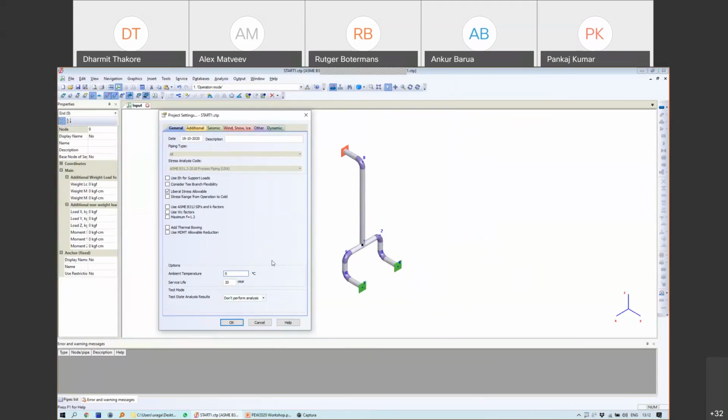My point here is, when you have minus 20, you can't do the fabrication at minus 20. When you're talking about Russia, I also work on a lot of projects on Sakhalin Island. The platform where this pipework is installed, all the structure and the empty pipework, sees the same ambient. So the question for me was: in your analysis, are you setting this to a low temperature because the fabrication will be at minus 20? No, it's not the lowest temperature.